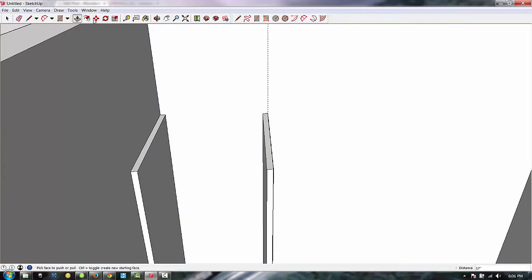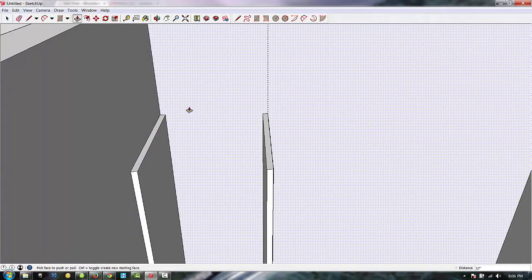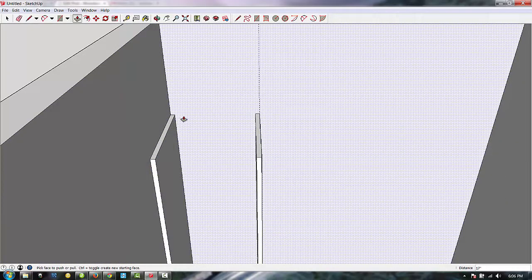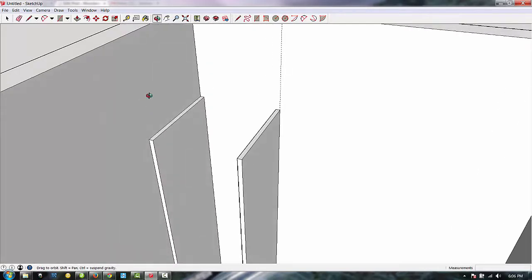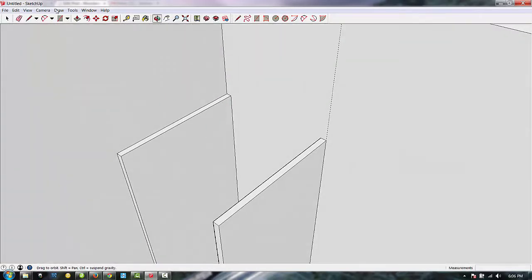So then in this case, I have a shelf that goes across the top that has a 1-inch overhang from the top of my left-hand tower. So I will rotate this to give myself a little better look. Go ahead and get to the corner, and then I will, with this being 17, I'll make it 18 inches. You can see it wants to snap to things that you place it next to. So I'll go 18, comma 3/4, and type enter.